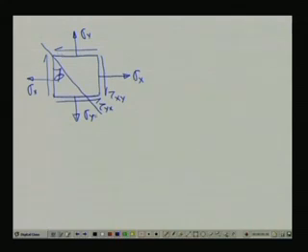What is meant is that this element is being acted upon by these loads. We know these loads, but if I make a plane cut at some angle, say here I have just given as phi, then what will be the stresses at these locations? Although here we can see sigma x of some magnitude, at some other plane the sigma x will change its magnitude, and those magnitudes could be larger than the sigma x we can see apparently for this plane.